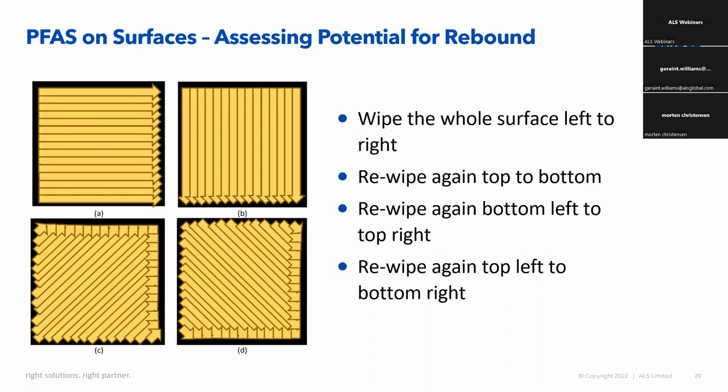So just to highlight that AFFF can form these kinds of surfaces on pipework and tanks, and there is this issue when we're switching out the foams, and there's a growing market for this at the moment. We do need to be aware that you can get rebound from this residual PFAS that forms crystalline solids or supramolecular assemblies on the surfaces of tanks and pipework. If you're not aware of that when doing this foam decon, then this can potentially rebound into the